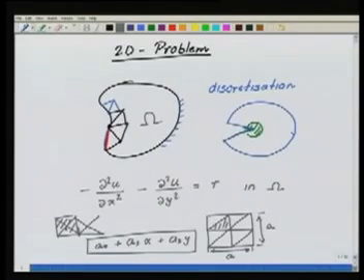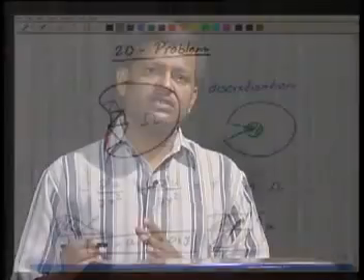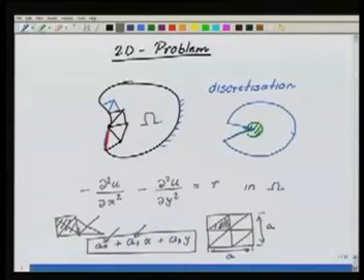So over each element here, I would like to construct a piecewise linear approximation. The piecewise linear approximation means that over the element, the truncation of the basis functions are linear polynomials. Now, how many independent functions do we need in an element in order to completely define a piecewise linear? The answer is that since this piecewise linear incorporates 3 unknowns, we need 3 independent functions.